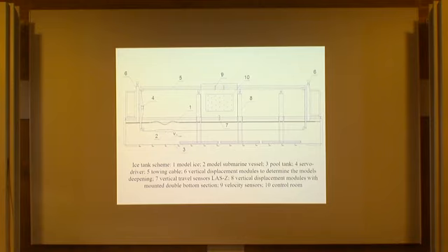All the projects have various displacement, length, form of cross sections, and protruding parts. The other 6 were very simple models of submarines in the form of bodies of rotation of teardrop shape and ellipsoid of rotation, preserving the main characteristics of the project: length, displacement, and the area of the midship sections. The value of protruding parts was taken from the volume of the manufacturer's models.